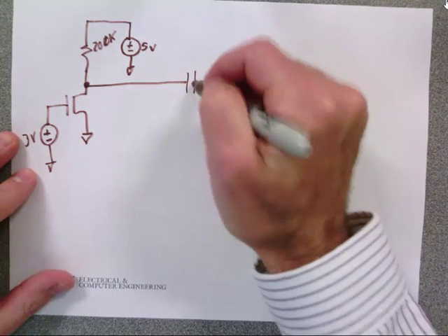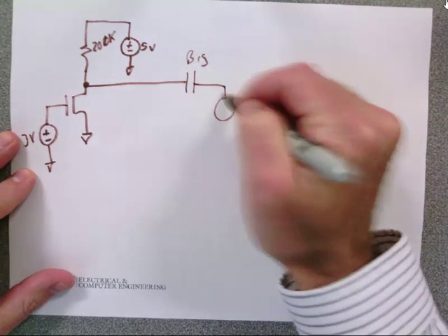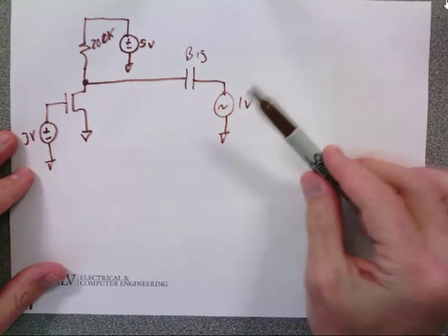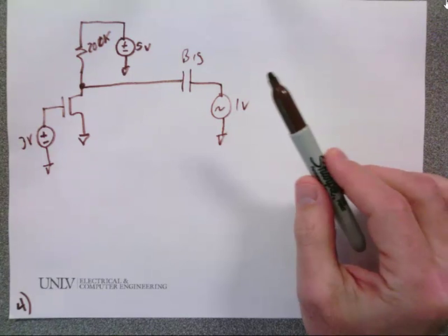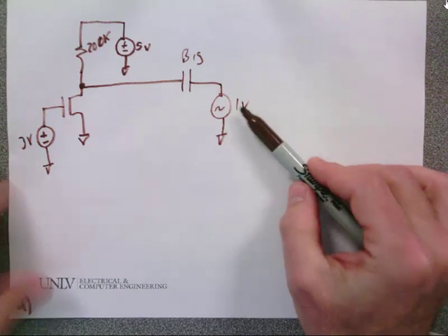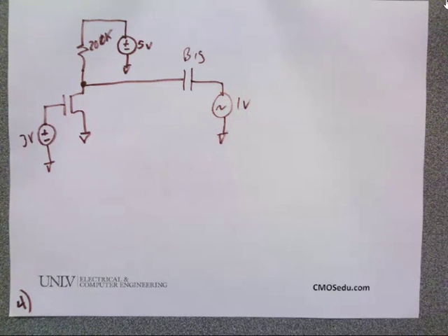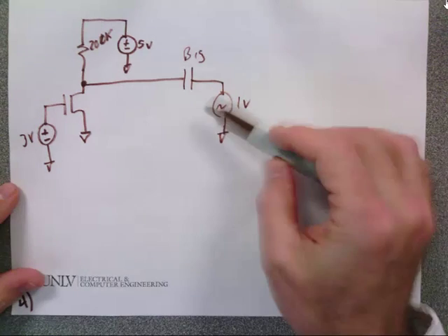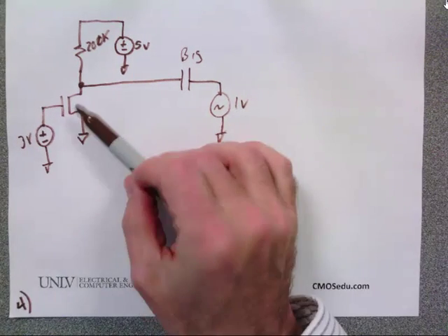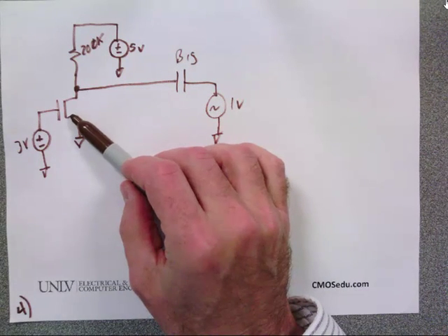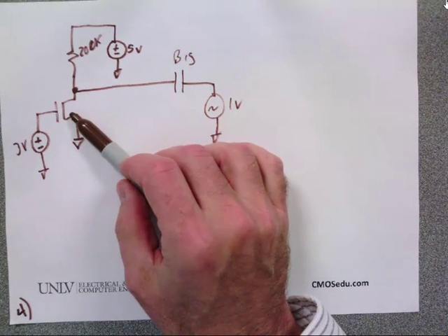So if I apply, okay, we're going to do something in a moment called small signal analysis. When Spice does small signal analysis, or we do small signal analysis, we assume the signals are small. However, we replace the models with linear R's and C's and what have you. In Spice, when you do a small signal or AC analysis, they replace the devices with their small signal model. In about 10 minutes, you'll feel better about small signal models.